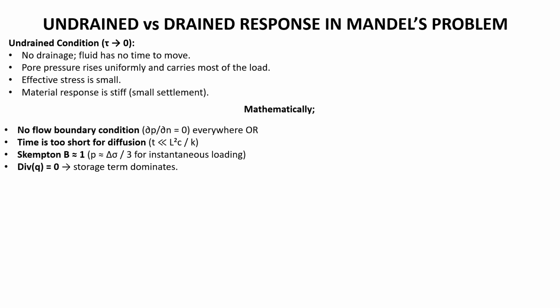One thing I would want to highlight is Skempton's coefficient, which is equal to 1. What this means is that almost the entire load is initially taken by the pore pressure, exactly what we expect for an undrained condition. So we say that the storage term dominates this particular phase of the simulation.